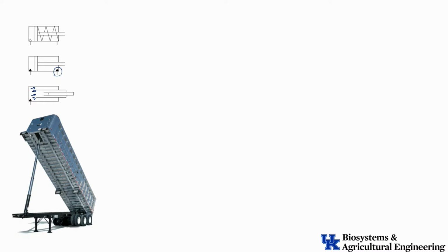When we start getting extended out, with only the last section or two, we only have the pressure acting on a much smaller area. So the force that it can develop is a lot smaller. And in this particular case, it makes sense. And you could do the statics on this and think about this.